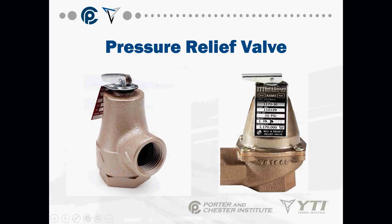If that boiler happens to reach 30 psi and above, the little spring that is inside here will pop up and water will come rushing out of this relief valve and usually makes people go into a panic. Once the pressure reduces below 30 psi, that spring will close and the water should stop. That is not always the case.